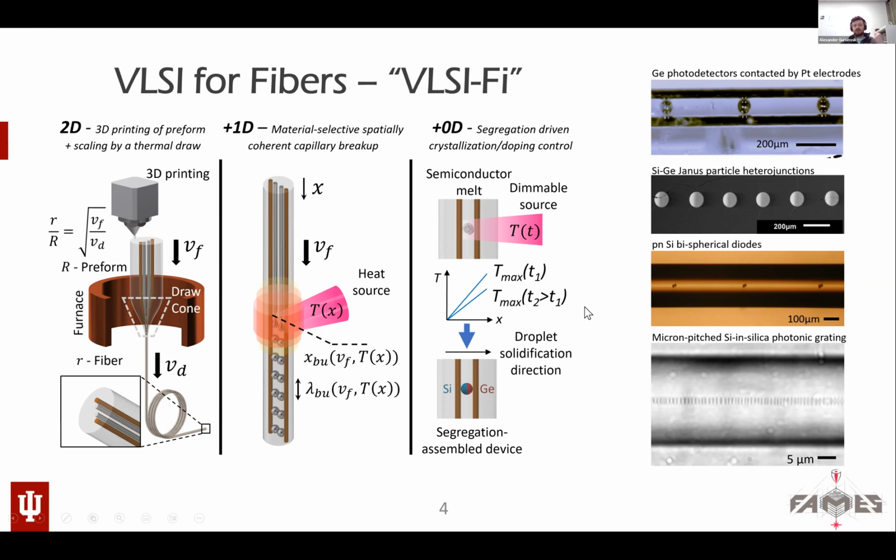So that's different from what you find usually in silicon wafer processing, or in germanium wafer processing, or in 3-5 semiconductor wafer processing. In wafer processing, you start with a substrate material that is well defined, and any device that you will get out of the processing, CMOS compatible processing, will be a device that is a derivative of a substrate material. You're limited, in other words, to a specific material platform. In fibers, you can combine any materials in any combination of cores, as long as they are liquid at 2000 degrees Celsius. You can cram them all into one fiber.